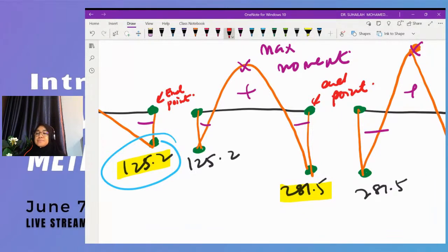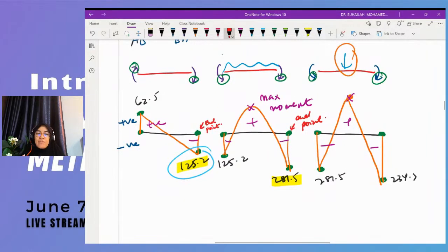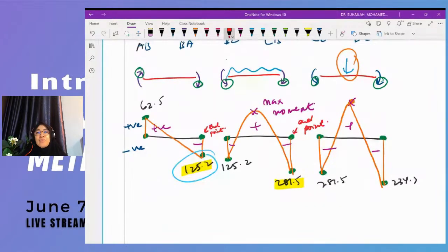Okay. So this is actually the bending moment diagram that we can sketch from the moment values that we get from the table. Careful with the loading on top of the member. For UDL, we have the curve shape, and for the point load we have the straight line, but it still has a maximum moment.